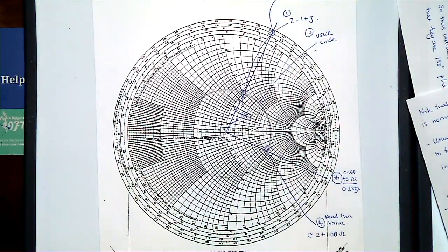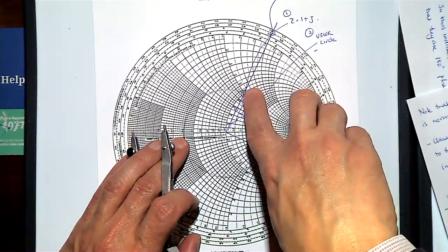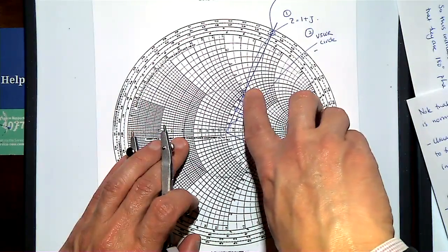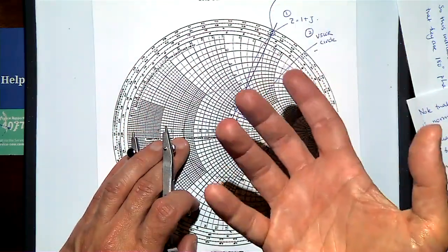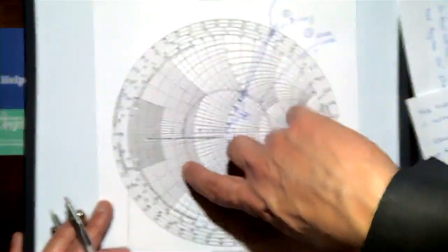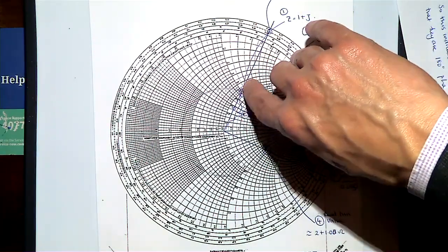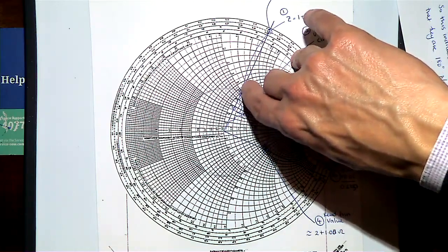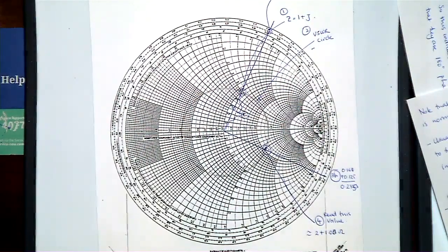Now, that enables you to calculate, if you had this particular load impedance and you were connecting it up with a line which had an impedance equal to the characteristic impedance, how the input impedance would vary, and you can make the line as long as you like. Essentially these are all the values of the input impedance that line and that load will at some time manifest.